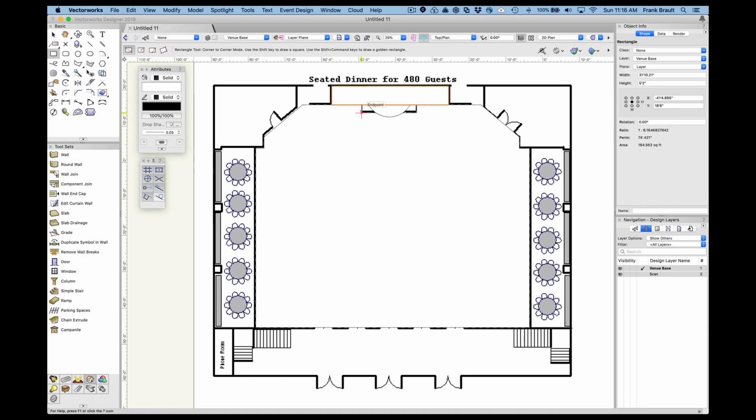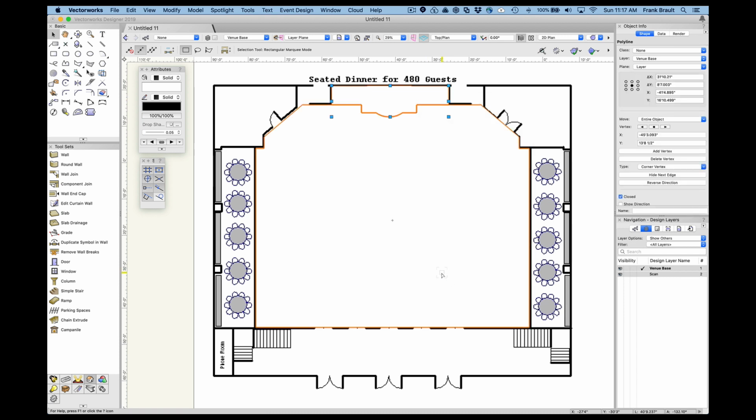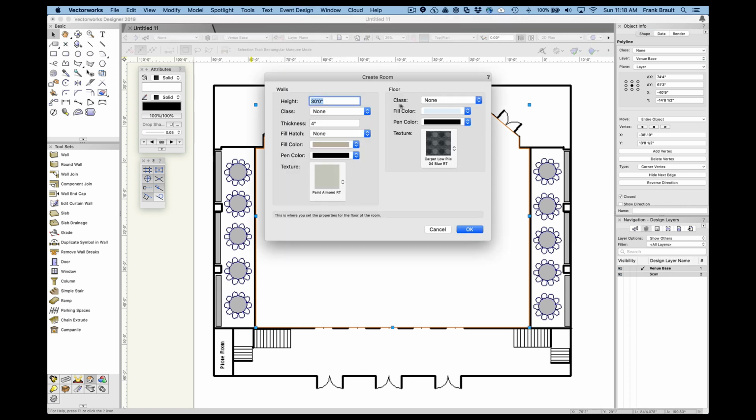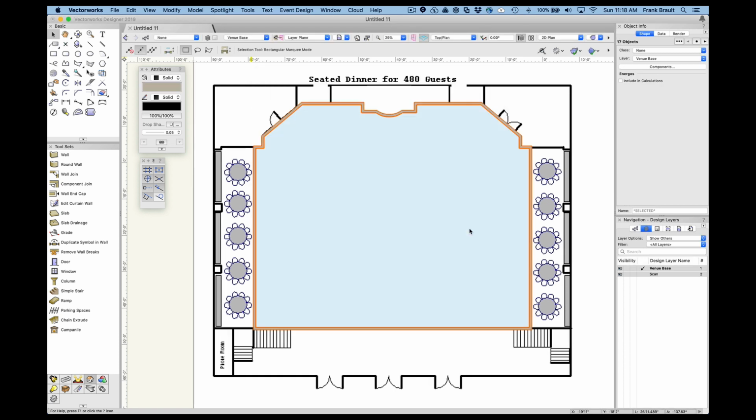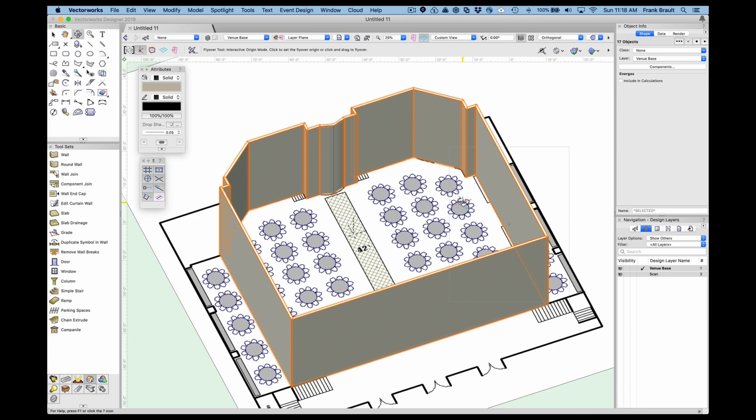Primarily, Vectorworks has conversion operations like combining surfaces, which are created with tools that create a closed figure like rectangles, circles, and polygons, and where you can use simple overlapping shapes to create more complex shapes that would be more difficult to draw all in one go. Then, you can use the resulting shape to create walls or other venue elements, such as floors and ceilings, and use the program's door, window, and other parametric objects to add the necessary shapes to capture the essential character of the venue.